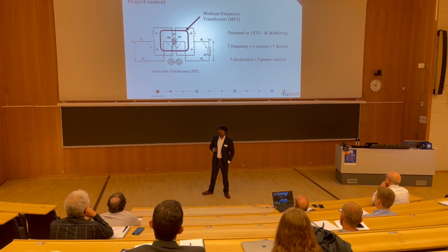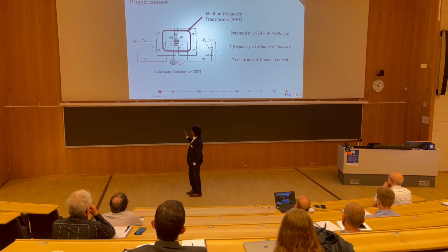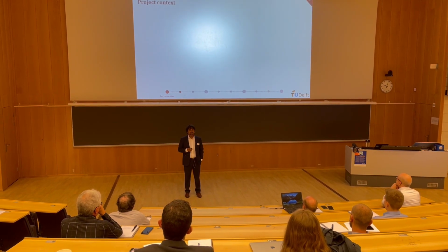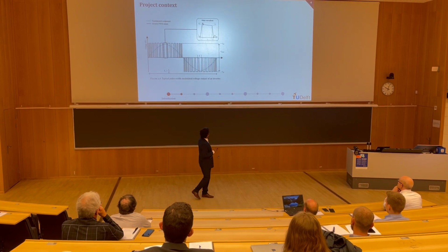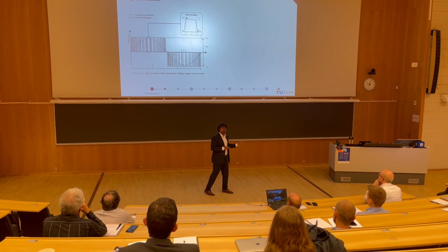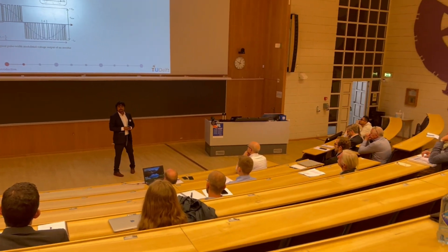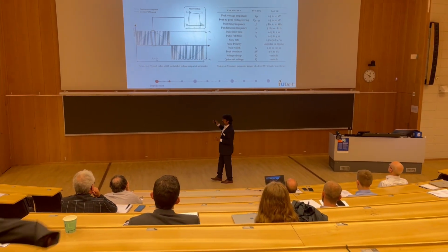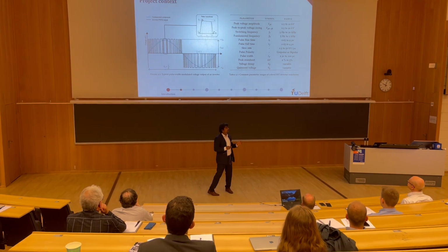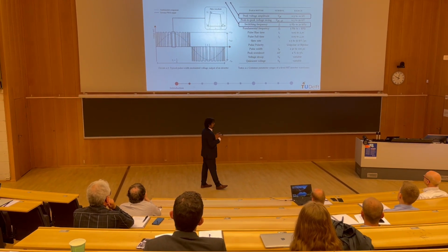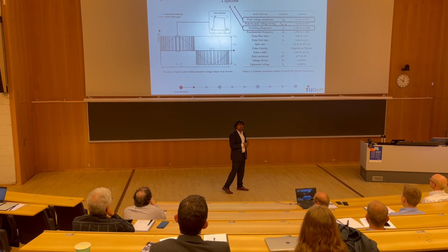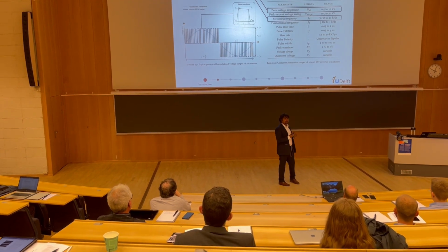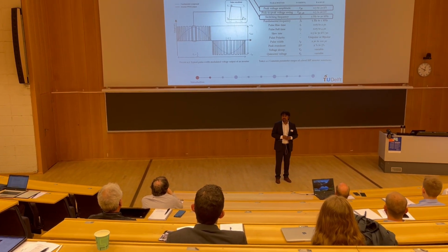But the consequence of this is that the insulations in these medium frequency transformers will experience a lot of different kinds of stresses, which have never been studied before. These stresses are characterized by a lot of different parameters, but the main important parameters are these two: the peak voltage and the switching frequency, which are known to degrade insulation lifetime.